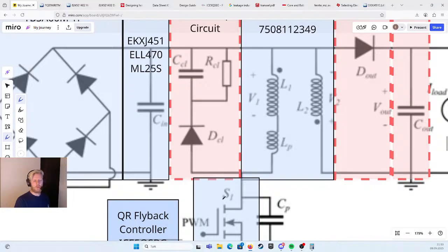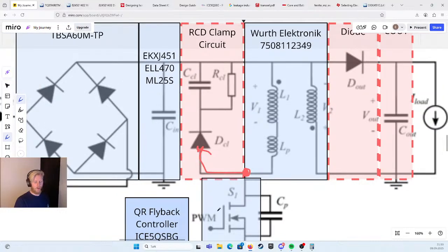But yeah, so when the MOSFET is off, we have a high spike here, which we determine based on the margin on the MOSFET. So the MOSFET can handle 900. We give it some margin, so that when it reaches 640-something, it will clamp here. Current will flow in this direction, and we will handle the energy that is collapsed here.